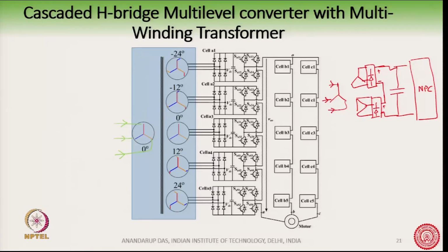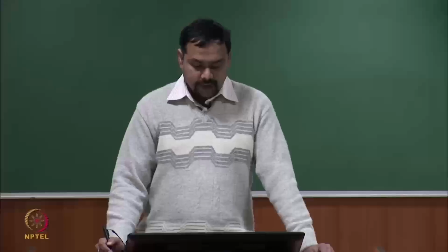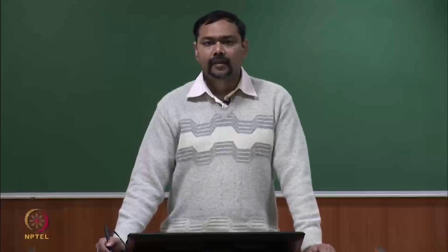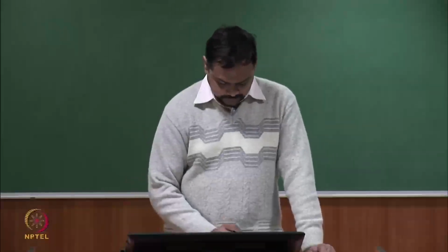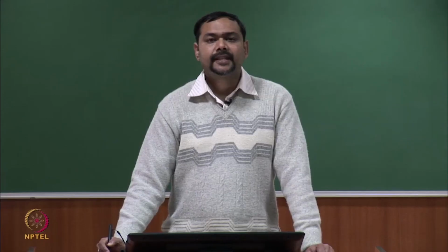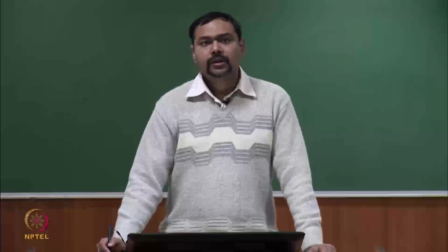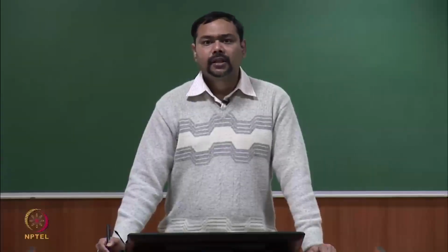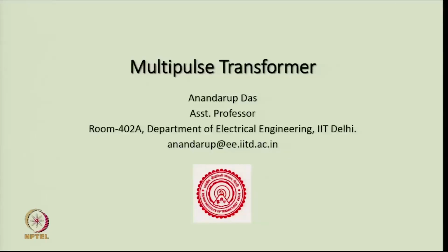When we talk about these higher pulse transformers, we usually talk about zigzag or extended delta connections. So, we continue with the multipulse transformer. Today's discussion will be on the zigzag transformer and how the zigzag transformer helps improve the input current harmonics. So, that is what we will study.